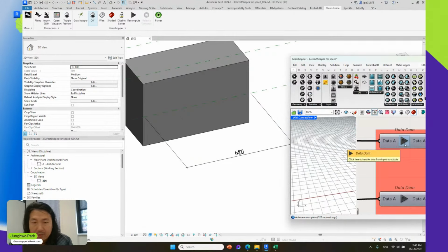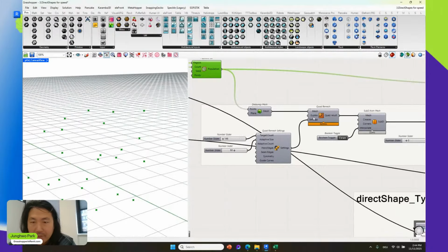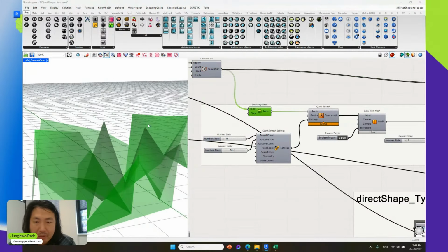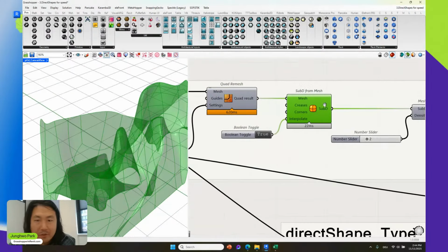And for one of the examples here, we have a box, right, in Grasshopper. And sometimes, just to play with it, I populate the points here, and we make this kind of mesh geometry. We could do quad mesh with Rhino's new features. Was it Rhino 7? I forgot. And then you can even subdivide it. So this kind of quad meshed element can be converted as a subdivision. And bringing this kind of geometry, I mean, modeling it in Revit would be almost impossible. With the help of Dynamo, you can do that. But Grasshopper is much faster when it comes to geometrical operations, right?